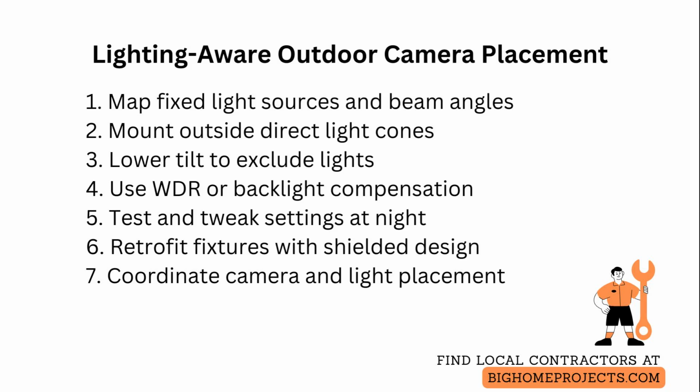Use cameras with wide dynamic range or backlight compensation and set exposure priorities to preserve subject detail in high contrast scenes, and test at night with a live feed to tweak settings rather than relying on daytime placement alone.